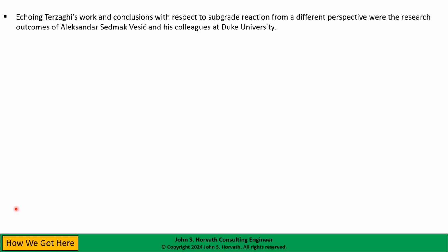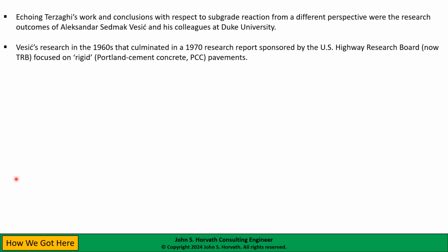I'd like to discuss one more body of work that echoes Terzaghi's work and conclusions with respect to subgrade reaction from a different perspective. And this is the research outcomes of the late Professor Vesic and his colleagues at Duke University. Vesic's research in the 1960s that culminated in a 1970 research report that was sponsored by the Highway Research Board in the United States, now known as the Transportation Research Board, focused on what we call rigid pavements, that is pavements of Portland cement concrete, generally reinforced Portland cement concrete.